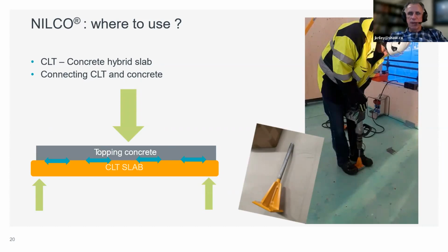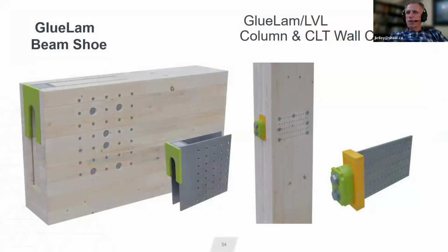We have to go through these steps to prove it, to make sure that it works under all conditions in North America. So we're doing that with some other designs right now. And whether that comes to fruition or not, we'll see down the road. But these are some of the other concepts that are all coming together pretty quickly in advanced mass timber design, because the connections between the column and the beam is where the huge expense is. And especially in seismic, we don't know all the ramifications of that yet.